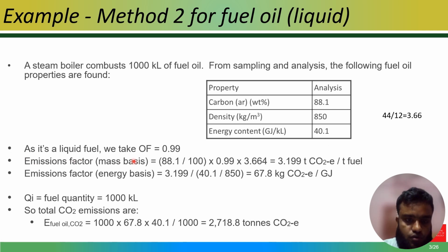Let us consider the oxidation factor, which I discussed before, as 99%. First of all, we have to calculate the emission factor. How can we calculate the emission factor? The emission factor is the carbon content in the fuel, so it's 88.1% divided by 100, making it a fraction.